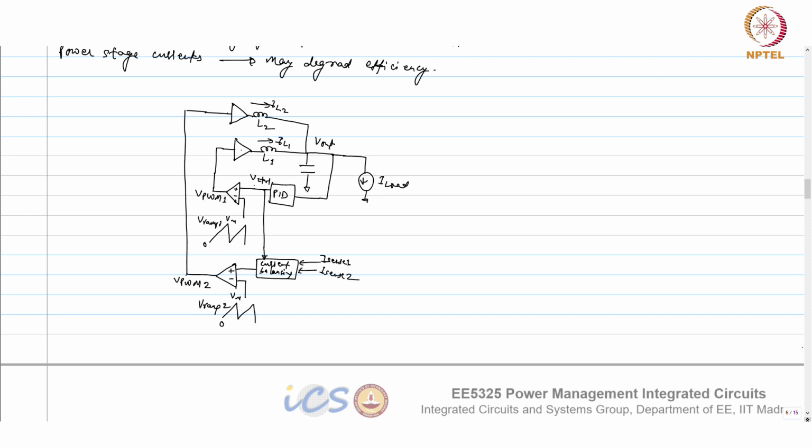But in the time-based approach, we don't get that problem, because you tap the phases and they are already all matched. The delays would otherwise cause a mismatch. Let's say I have 5 delay cells in the ring, so it's a 5 phase. I can tap 5 phases from there, but ensuring each delay cell is exactly the same or matched is very difficult. So the phase to phase mismatch may be there. That may cause a difference in the duty cycle in multi-phase.